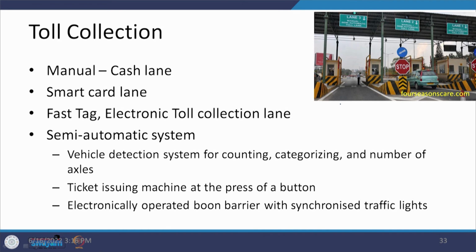Now, let us talk something about the toll collection. When you are looking at toll collection, we have discussed that there are possibilities of taking cash or it can be through a smart card, but nowadays we are more focused on the FASTag or the electronic toll collection. In the case of a semi-automated system, there is always a camera which is taking continuous flow into account, and therefore the counting of the traffic is there, and the categorization of that traffic is also going on at the back end,